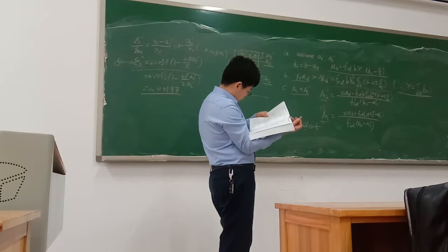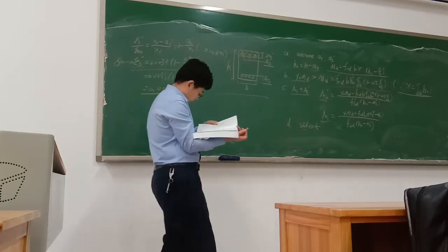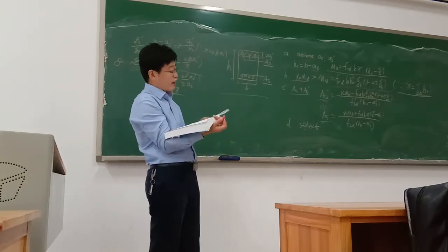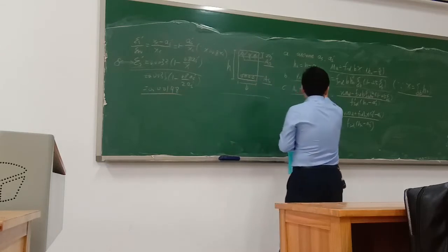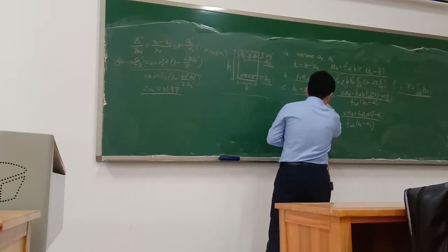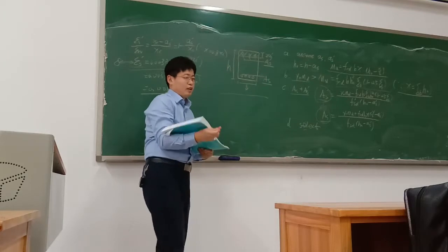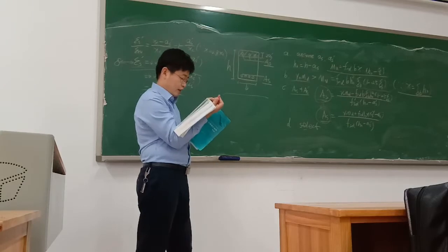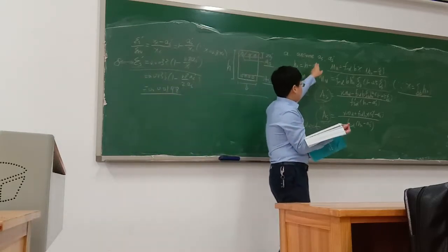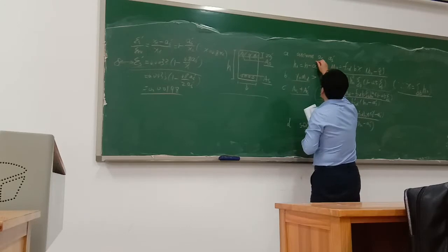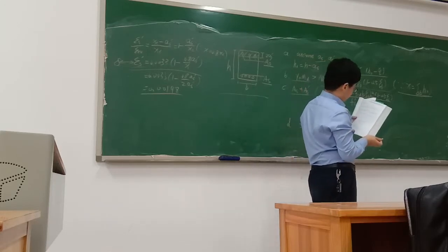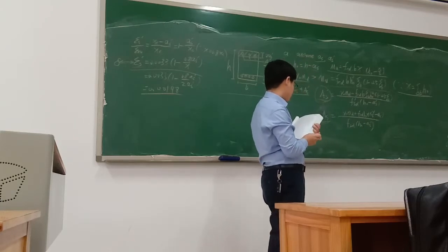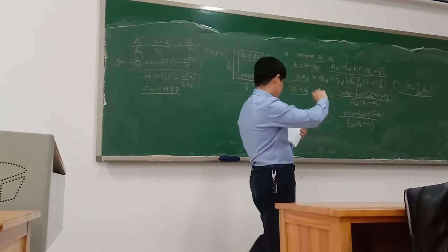And also, we told you about another situation, where we give you the compression reinforcement AS prime, and just ask you to calculate AS. This is simple. In this situation, you just assume AS, and then from the basic formula you can calculate x, x equal to h0 minus this.